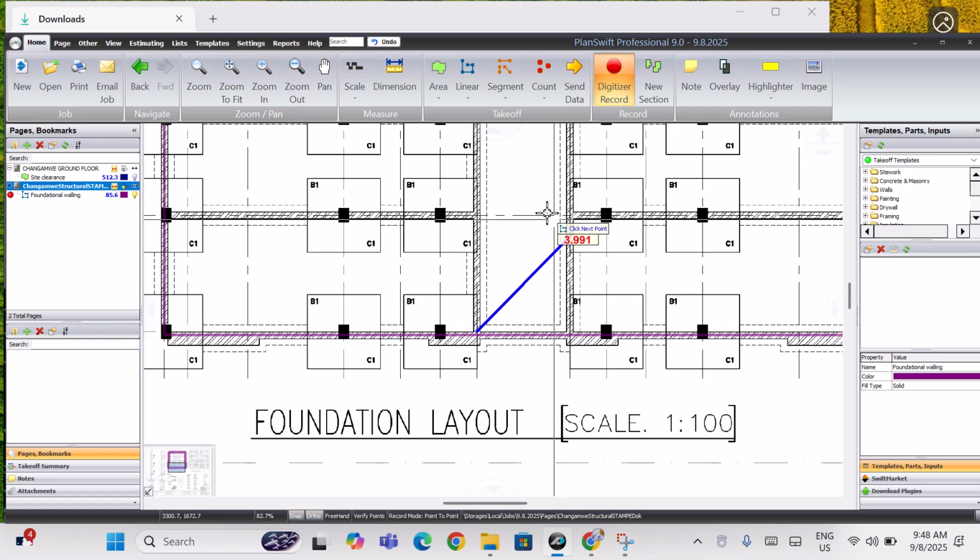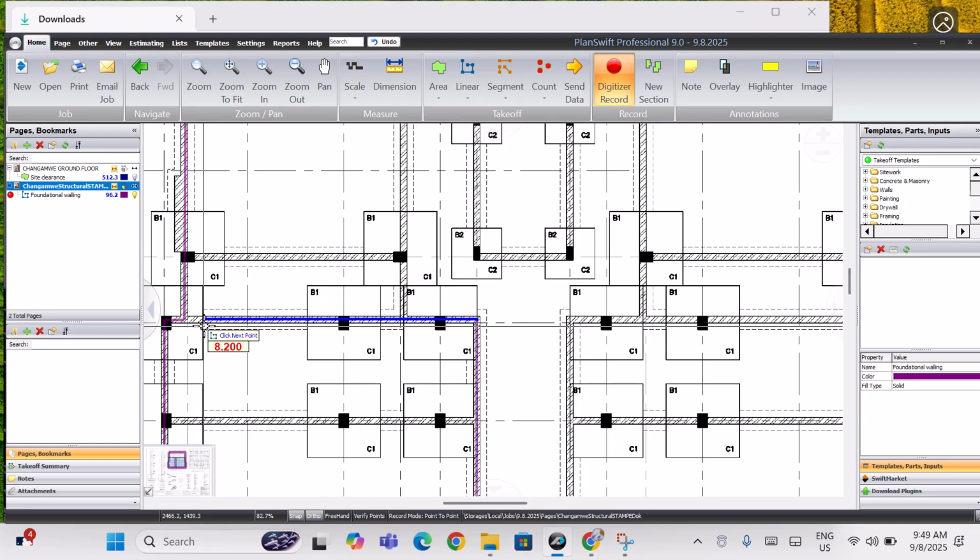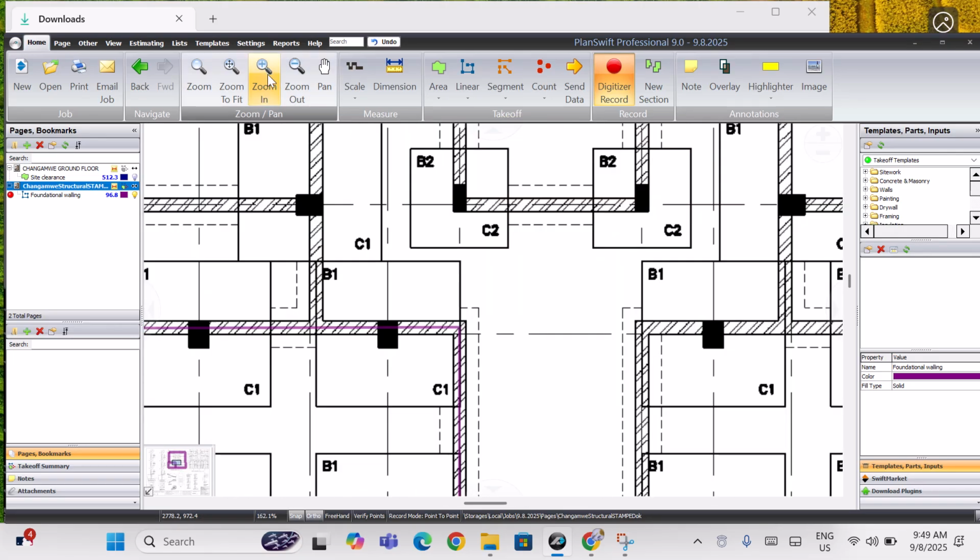Now you can zoom out, and yeah, there's a sharp turn to your left. Since it meets the other foundation measurement which you had already measured, just double tap. You tap once, then you right click, and it indicates a new section. Basically you start elsewhere, you zoom in, you can start here, which is not measured yet.